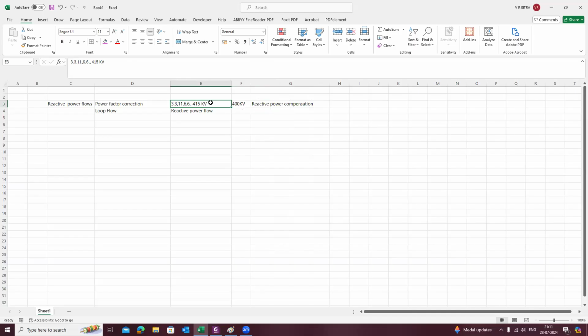And sometimes this reactive power compensation requirement could be a combination of both, meaning a combination of the reactor as well as the capacitor. Okay, for this, the best example is the metro. Suppose you take the metro or a traction. When there is a train which is running, the demand will be more. By that time the power factor will be lagging.